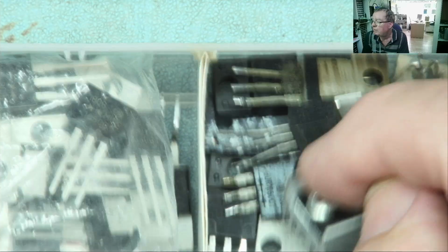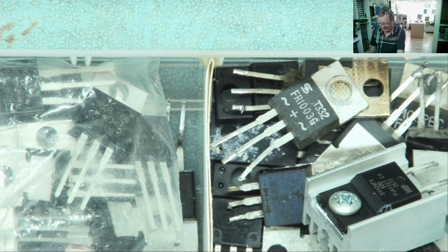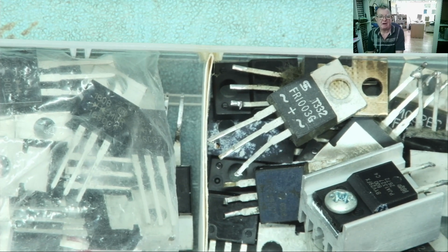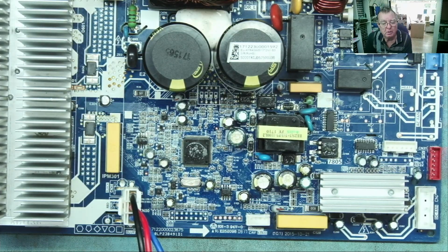So these are diodes you commonly find on the output of a switch mode power supply, and they are a common failure point. Sometimes due to short circuits on the output, but sometimes they just give up. And the last bonus one, we'll still call it number 13, why not, is something you will not find on a PCB or on the device, because the other number 13 is the customer, the owner of the device. They fail on a regular basis.